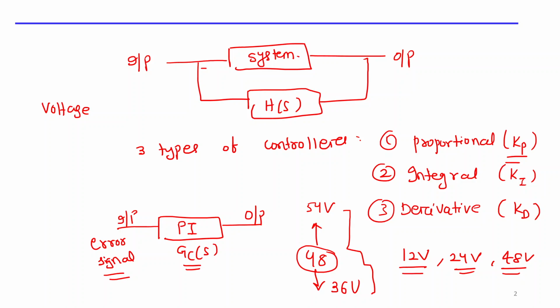The PI controller is just a controller that minimizes the error. It achieves steady state stability and makes the steady state error zero with an accurate bandwidth. We don't want our system to be slow, so the bandwidth should be properly maintained according to the frequency at which you are going to operate the system.